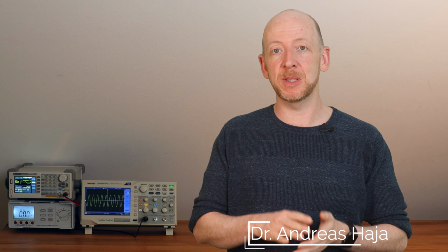Now let's quickly summarize the most important takeaways for you from this video. Firstly, a simulation has shown that the total resistance in a parallel circuit is smaller than the smallest of the individual resistance values in this circuit. And secondly, the layout of a circuit diagram can be changed visually without affecting the functionality under some circumstances. And then the sum of the currents at a junction point combined with Ohm's law provides you the basic equation for deriving the total resistance of a set of parallel resistors.